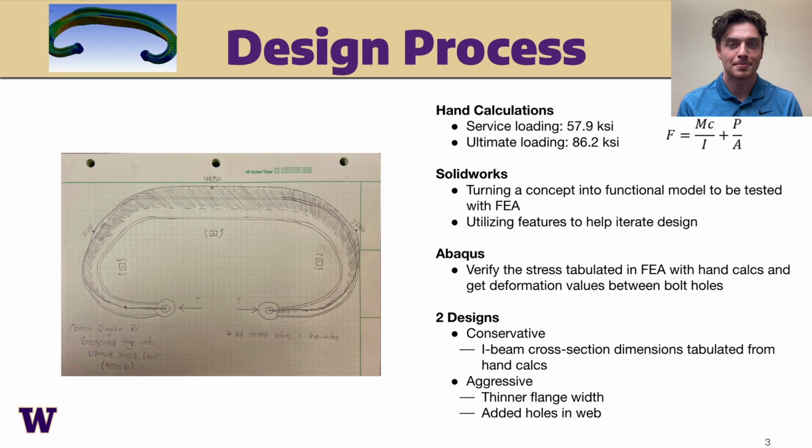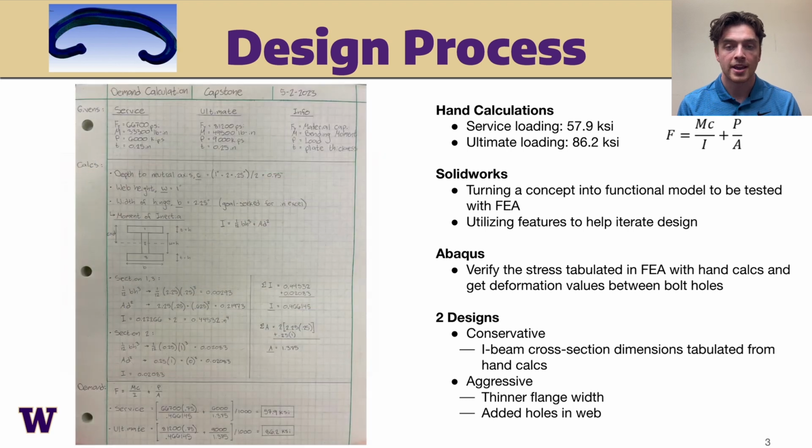The design process began by using the geometry of the original envelope to determine stress demands around the hinge. Due to manufacturing costs and construction simplification, we settled on creating a hinge that was built of multiple sheets of steel 4130 with a uniform thickness all welded together. This thickness would be determined by analyzing stress demands around the hinge and choosing one that would keep demands below the yield and ultimate strength of 4130.